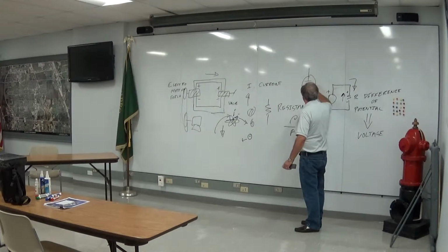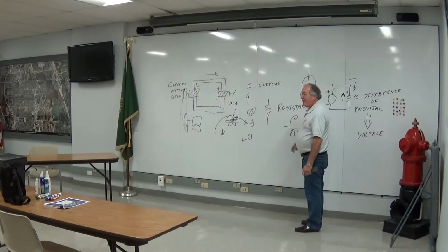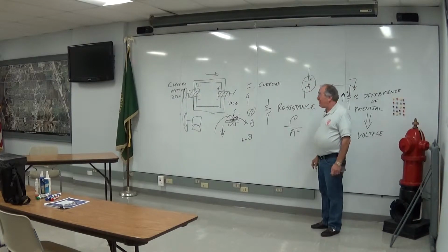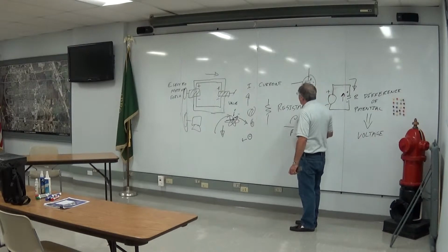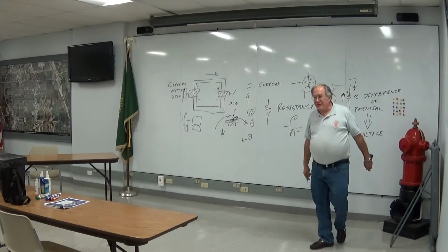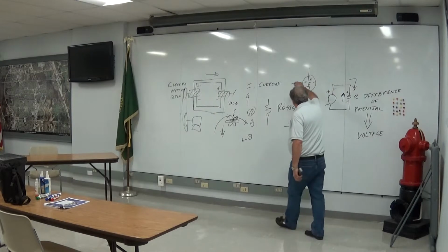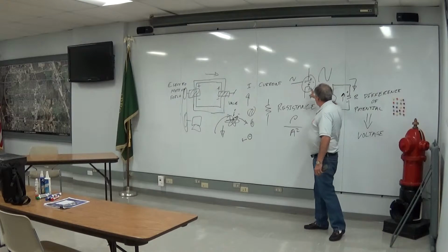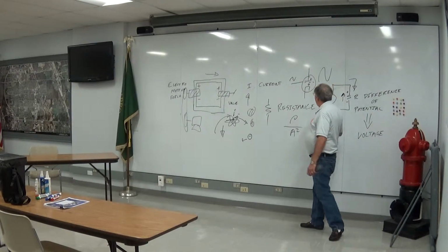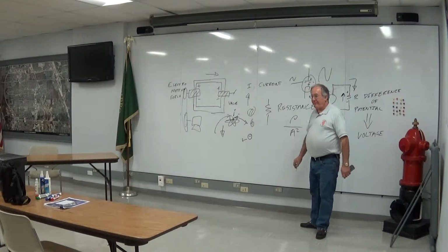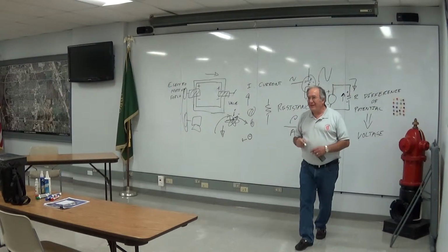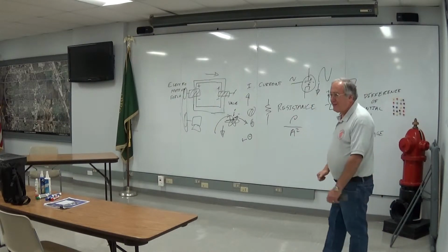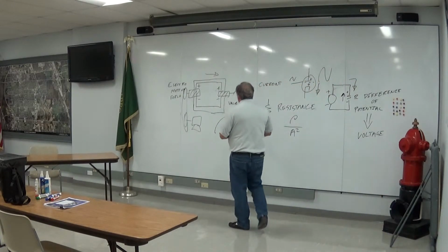There's a vacuum tube too. This thing called a cathode emits electrons. They're attracted to this very high voltage plate. They're regulated by the screen in the middle called a grid, which controls the space charge in the tube and allows a tiny current here, alternating, to become a larger one here. The little voltage swing here produces a large voltage swing there. But guess what? The current is flowing that way, even though the electrons are flowing the other direction. Strange, but that's just something you have to get used to because them's the rules. There's no other way to explain it.